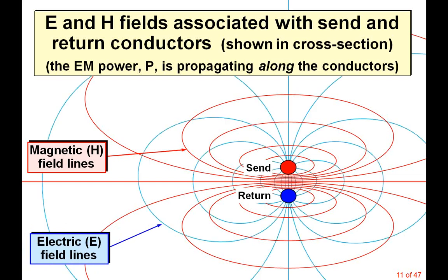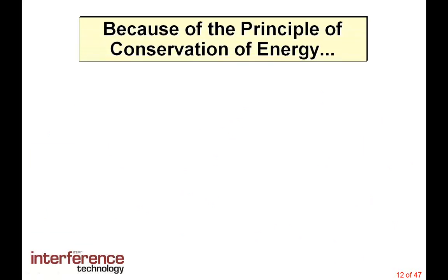And we can draw electric field lines like that. You notice the electric field lines always terminate on the conductors, where the magnetic field lines never do. Once again, where the electric field lines are close together, it tells you that there's a lot of electrical energy in that region of space between the wires. Of course, if I was to draw the PVC insulation around these wires, then it would modify these field patterns. Well, this would modify the electric field pattern because of its increased dielectric constant, its permittivity.